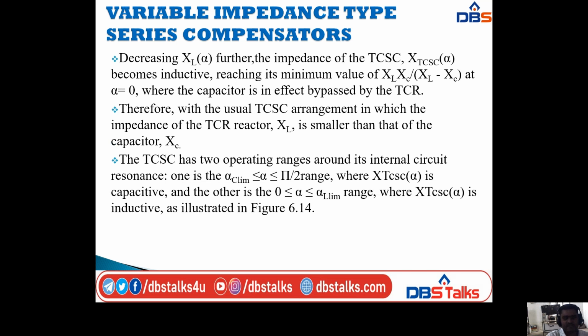Decreasing this XL of alpha further, the impedance of the TCSC, that is X TCSC of alpha, becomes inductive, reaching its minimum value of XL into XC divided by XL minus XC at alpha equal to 0, where the capacitor is in effect bypassed by the TCR. Therefore, with the usual TCSC arrangement, in which the impedance of the TCR reactor, that is XL, is smaller than that of the capacitor, that is XC,